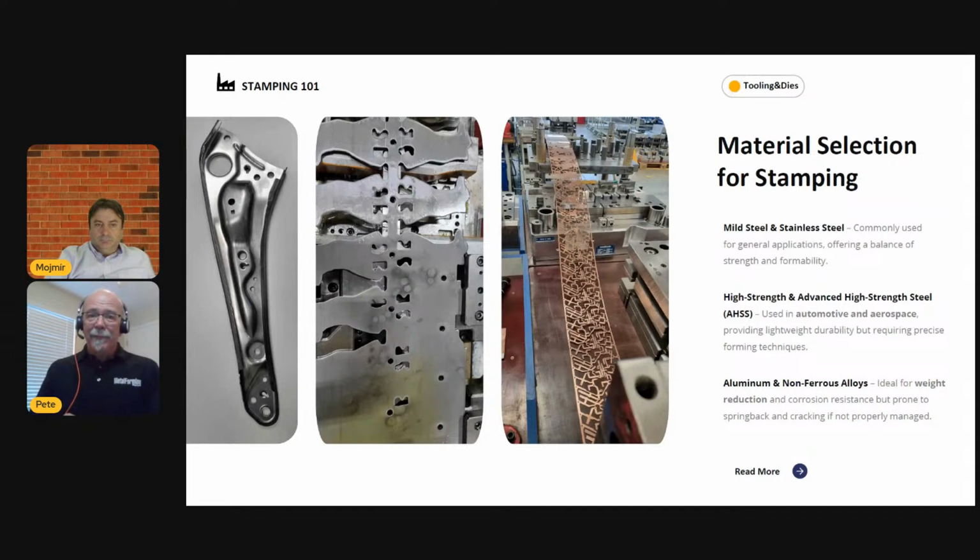Grinding wheels, sandpaper, right? Abrasives. So aluminum, although it appears soft, it looks smooth. That aluminum oxide layer that's on the surface is very, very abrasive. This is why you experience galling in aluminum dies. A lot of times we think, oh, the material's soft and gummy. It's actually abrasive. It's abrading and ripping and tearing, generating a lot of heat and causing adhesive wear as well.